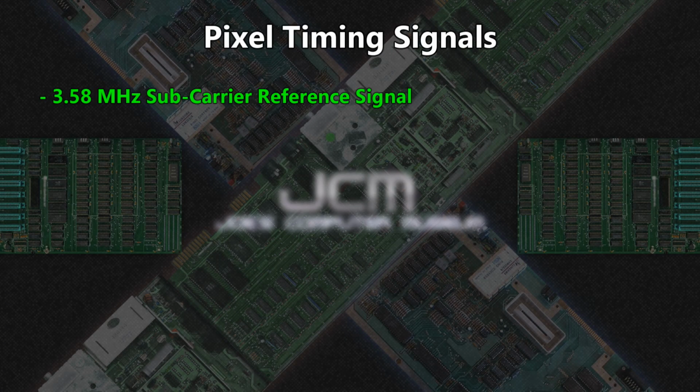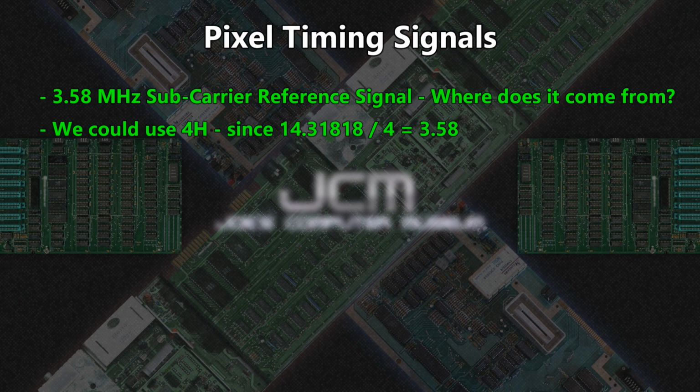Now let's assemble the 3.58 MHz reference signal. The 3.58 MHz subcarrier reference is used to generate all of the color signals we'll need later. We have to get our 3.58 MHz source from somewhere, and you may be thinking we can tap it straight off of pin 7 of the horizontal counter, since that's 1/4 of the 14 MHz main clock. But not so fast. That's a trap for young players.